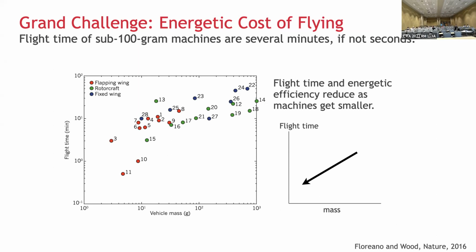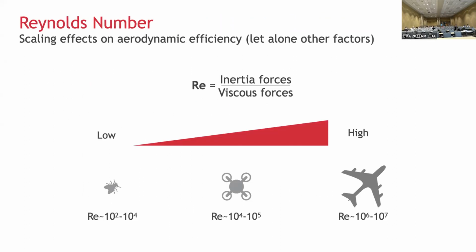And there are lots of reasons behind this. But one reason that it's harder for smaller robots to get power autonomy is also because of the aerodynamic efficiency, right? Which is characterized by the Reynolds number. If you are in the field of flying robots, you might be very familiar. If not, that's okay, right? Reynolds number, of course, if you work on micro robots, you know this very well. So Reynolds number is basically a ratio, the proportion of inertial forces over viscous forces.